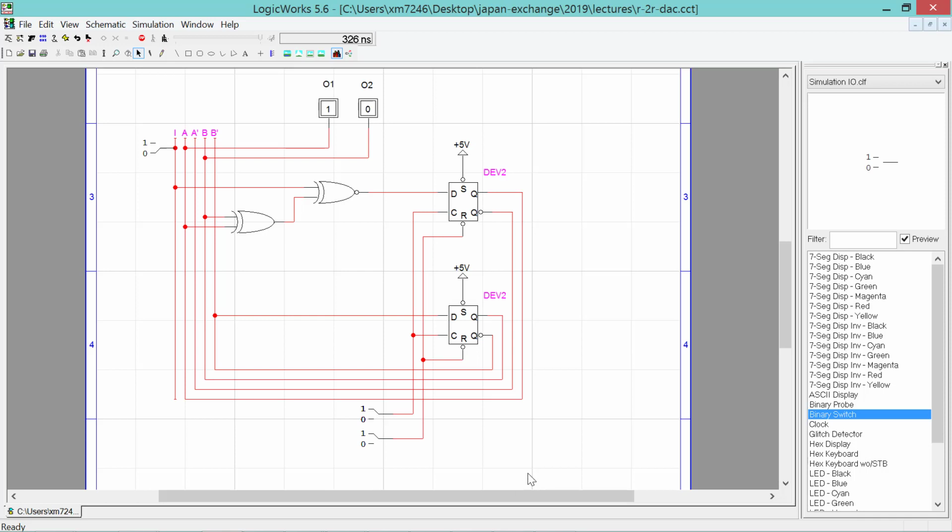So we see here from the simulator how our state machine works in action. We have our combinational logic here, and we can add this wire and the wires here and here. Those act as our combinational logic, and our register is represented by these two flip-flops here.